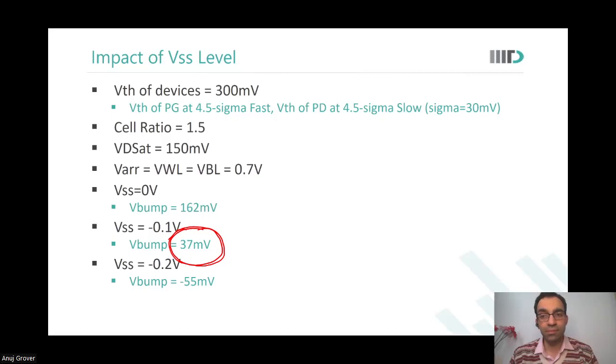The power efficiency, because I want to modulate depending on my frequency of operation. I want to save the load. We saw that when the load is not very high, let me not consume too much power. Let me operate slower and let me go to a lower voltage. So the entire attempt of going to lower voltage was to reduce power consumption. Am I right? Yes, sir. If power is not reducing, then what's the point in going to lower voltage?